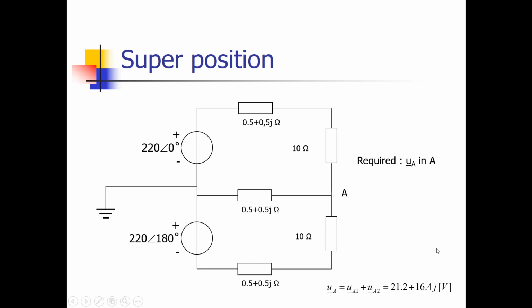So what we have seen is that for complex circuits with AC voltages, all the rules for superposition still apply, and that makes life still much easier to calculate a voltage or a current at a specific spot.